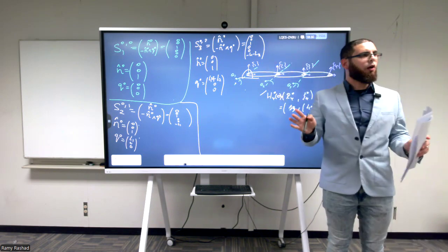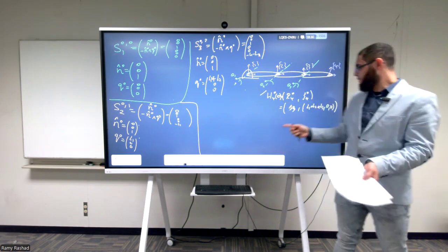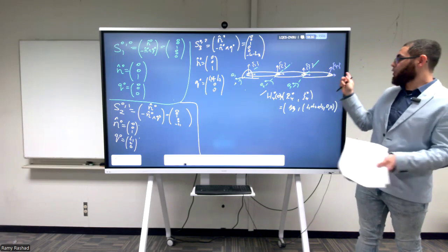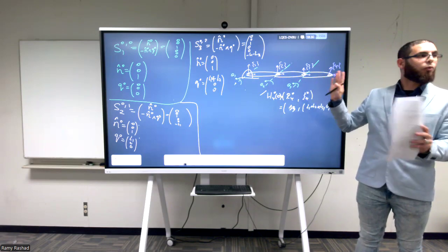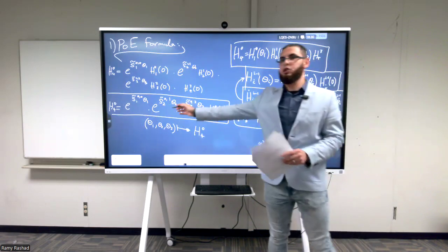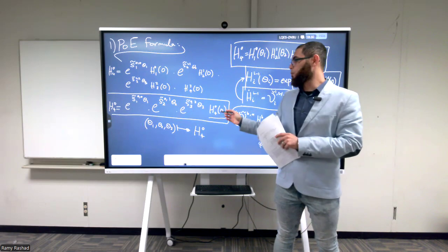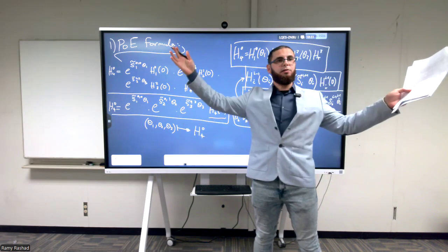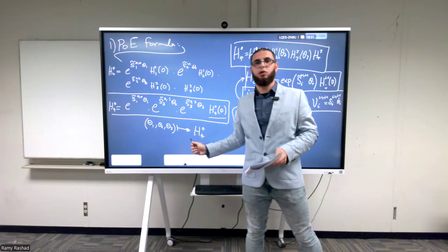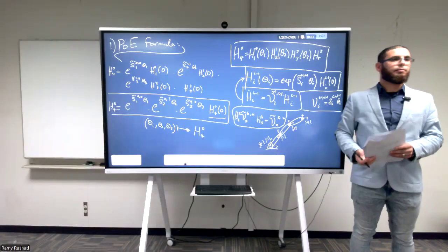Take these numbers. Again, we're talking about numbers here, something you can easily program. If you have this robot, you can do it by inspection. We only drew one drawing. We looked at the robot in this home configuration. We take all of these numbers, plugging them in this expression, which is something you can put on the computer. You're going to be working with that. You're going to put this on the computer, and in the end, you're going to get a huge homogeneous matrix transformation that will map. You give it 3 angles, and it will give you a homogeneous transformation that corresponds to the location and the angle of it in the 0 frame.